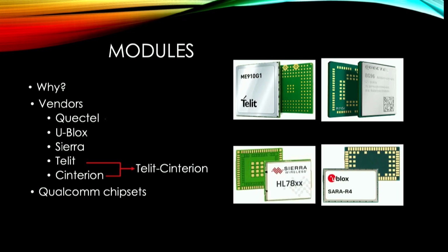Often, if you want to get a development kit for one of these devices, for every one of their modules, you have to have a development kit. It gets kind of expensive. Cinterion came out with one that had a socket. You could buy 2 sockets for one development board, cover every module produced. Big savings. It costs a little more than most of the devices, but again, I can test and interact with all of their devices using one $700 purchase versus $300 each to get through their whole series of devices.